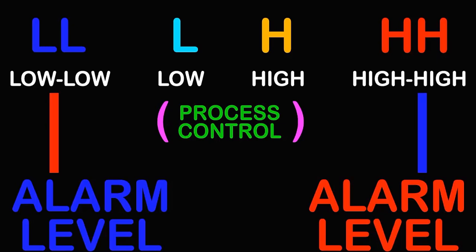It doesn't have variable heat. This heater is either on or it's off. And the way that we'll control this heater, we're looking at an analog signal from a thermocouple that's telling us what our temperature is. And let's imagine we have it scaled from 0 to 100 degrees. So in our program, we have a low and a high limit programmed into our control logic.